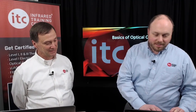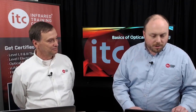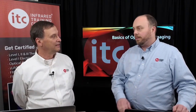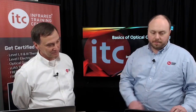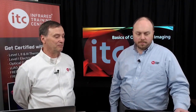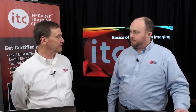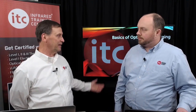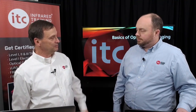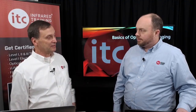Okay. Yeah. Let's see. Another question coming in here from Grayson. Can you use an optical gas camera on DTM valves for LDAR in an oil and gas refinery? Absolutely. I've got so many videos of difficult to monitor locations. And that's the preferred method. They'd rather you not climb up into an area where you could risk falling or risk opening, closing a valve or tripping something. So the OGI cameras, we have all the way down to a 6-degree lens that you can put on these cameras for long distances. And some of the biggest leaks we found have been in the difficult to monitor locations.